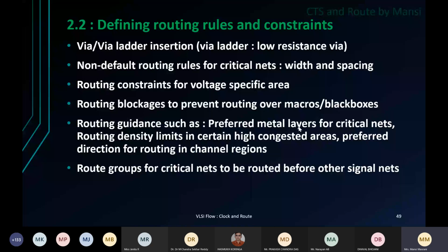What do you do when your whole design is shut down and then you power on the design? Immediately the clock starts flowing and your flops start working and you start taking the output? Or you try to set the design first at a certain Boolean value, I mean, you set all the flops to 0 or 1, something like that. Using reset. Yes, so reset, set, enable pins, clear pins, all these pins are critical.